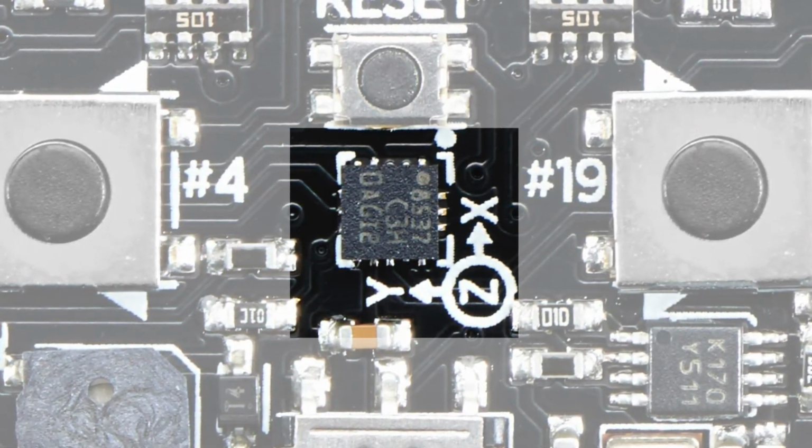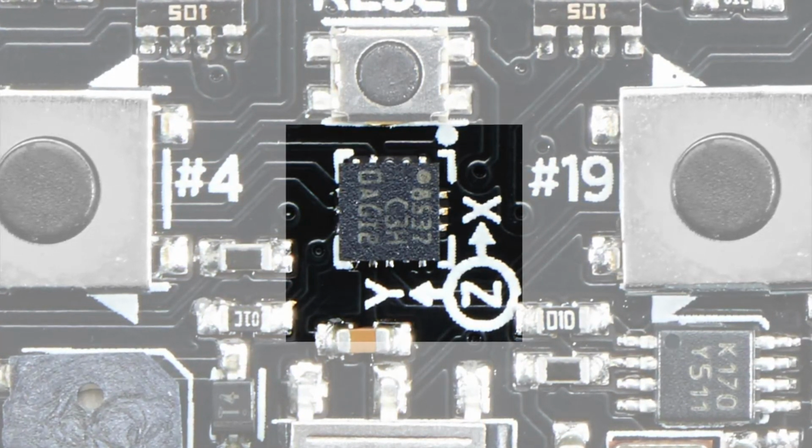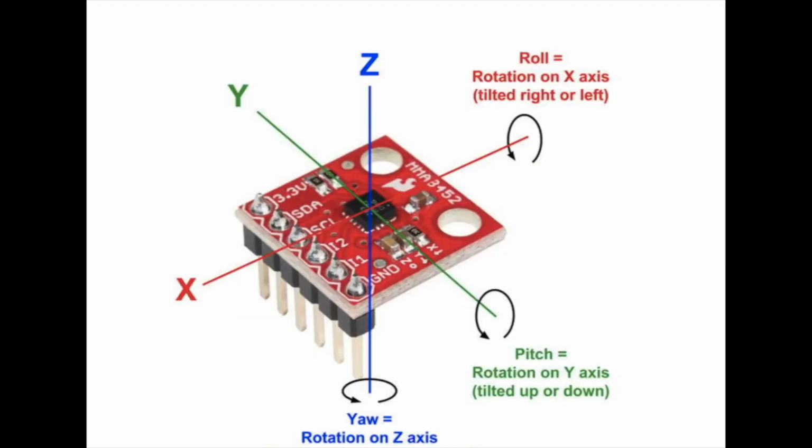Accelerometers are popular devices that are in your smartphone, Wiimote, or other devices that sense tilt, gravity, motion, and tap effects. An accelerometer like the one included with the playground measures relative movement. Ours measures in 3 directions. Any change in the location of the accelerometer chip will be registered as changes in the values it sends out. You can use this to detect movement in any of the directions, or you can pull the X, Y, Z values and use the values to see which directions the motion has taken place and how much it has moved. If a project needs to detect movement or measure a movement, an accelerometer is a perfect fit.